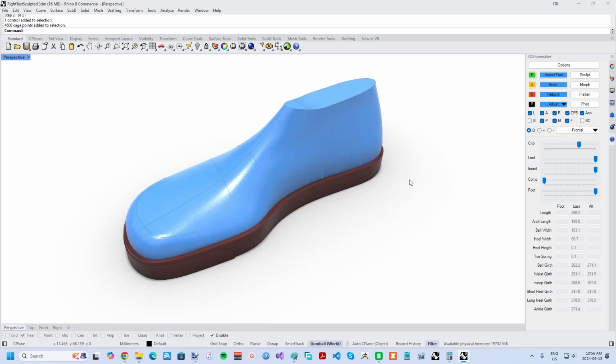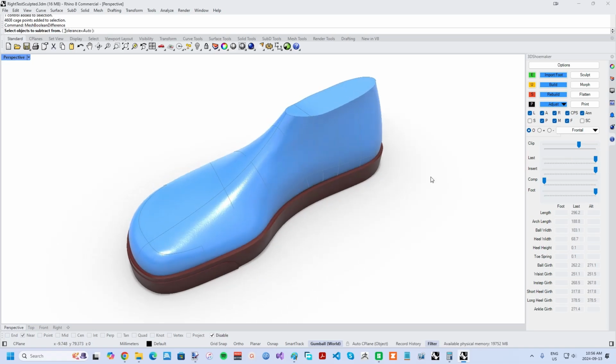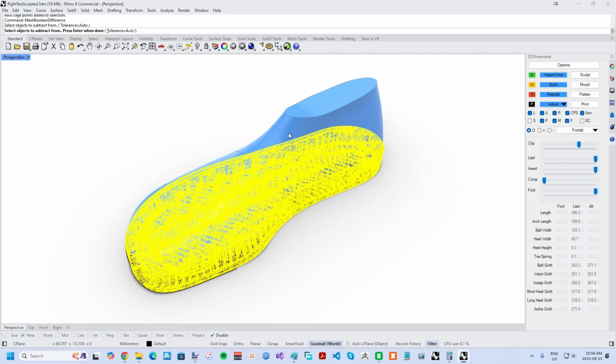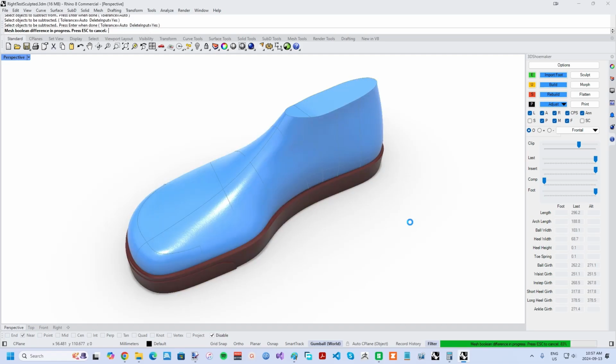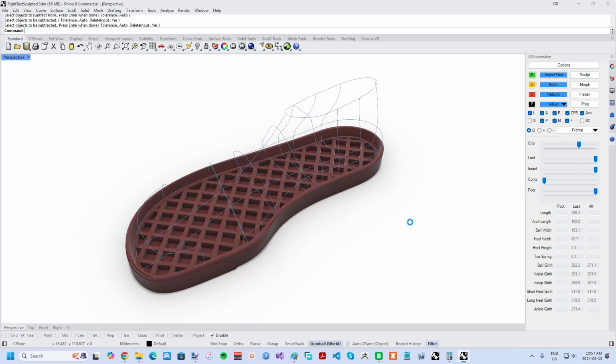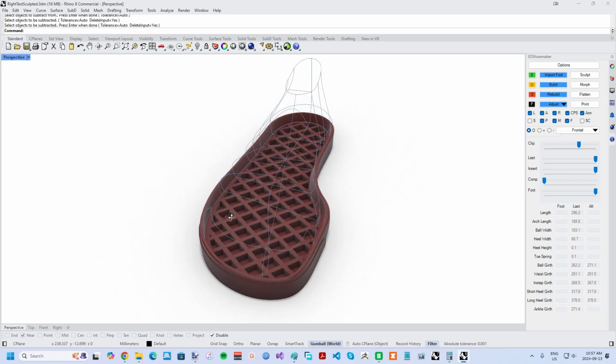For example, I like to morph component geometries that are filled in on the inside such that the target shoe last can be subtracted to get the final result. The advantage of this is that the inside of the component geometry ends up being exactly the shape of the target shoe last and not subject to any deficiencies of the morphing algorithm.